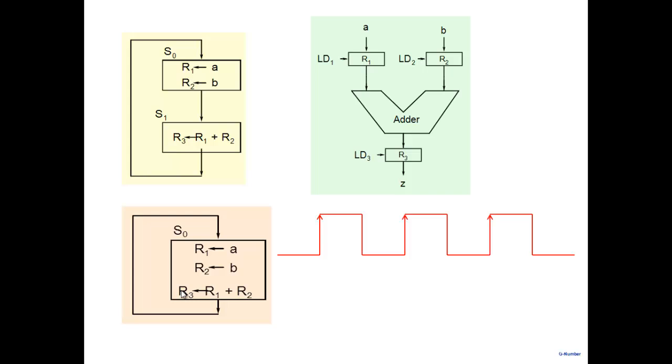latching it onto that. So if I compare these two, what is the latency? Latency of this in terms of clock cycles? When does the data become available? 2 clock cycles? What about the latency here? Latency means from the time a data is read to the time when the output corresponding to that data appears.